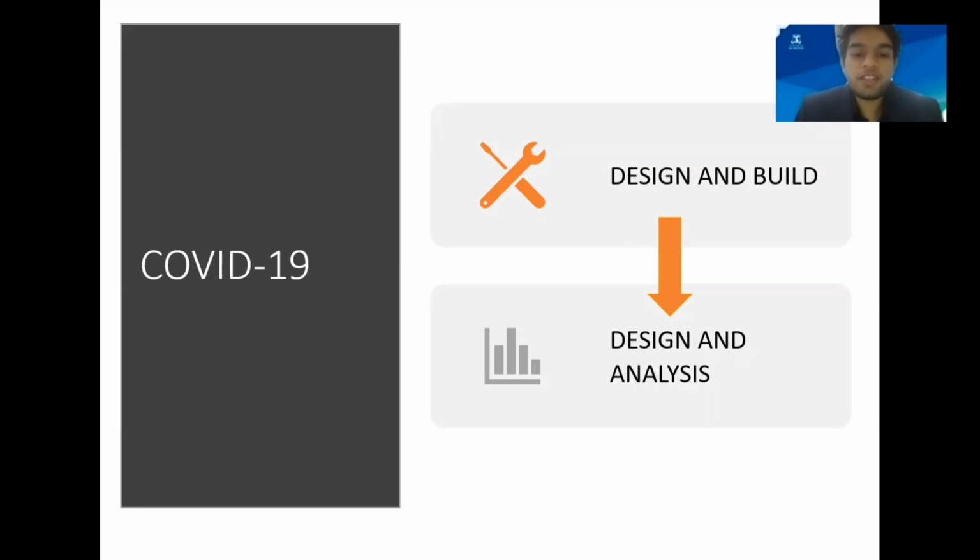The aim of this project is to design and analyze the efficiency performance of smooth surface compressor blade, of which the geometry is supplied by our industry partner Dyson, in a linear cascade simulated through computational fluid dynamics, Reynolds average Navier-Stokes analysis. The blade design will be focused on the ease of manufacturing techniques through interchangeable parts of the blade responsible for the surface texture.